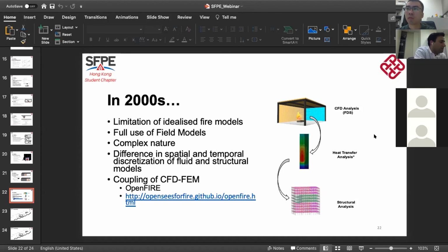But in CFD, you are putting in these values, and CFD also has some limitations. So it is very difficult to say that CFD completely represents real fires and the engineering models do not. Currently engineering models are good enough to give reasonable, or at least qualitative, analysis. For quantitative, it is a trade-off of accuracy between both of them. So the most important thing is you have to understand what assumptions you are using in both models.